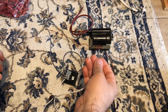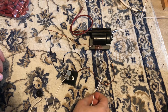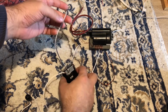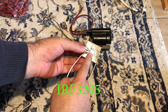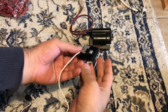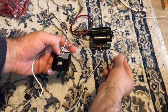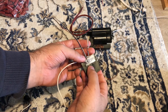This part, the midpoint, will be connected to the positive side of the battery, and this part, the main winding, will go to the drain of the MOSFET. This is an IRF3205 MOSFET. You need to use a heat sink because it will heat up a lot, so I use a tiny heat sink here. The third terminal will connect to the gate of this MOSFET.